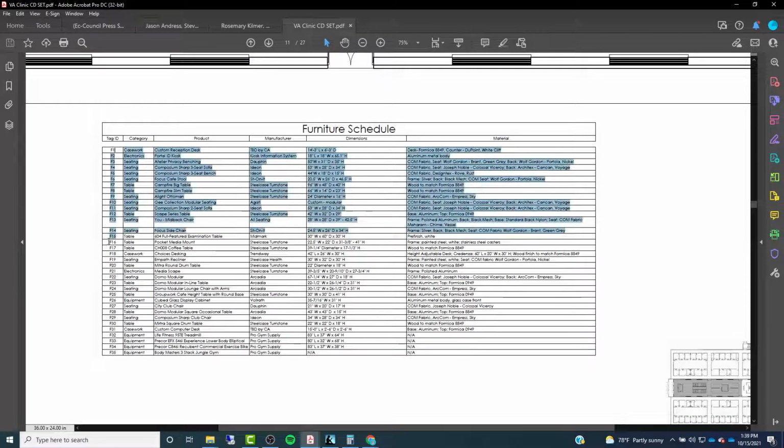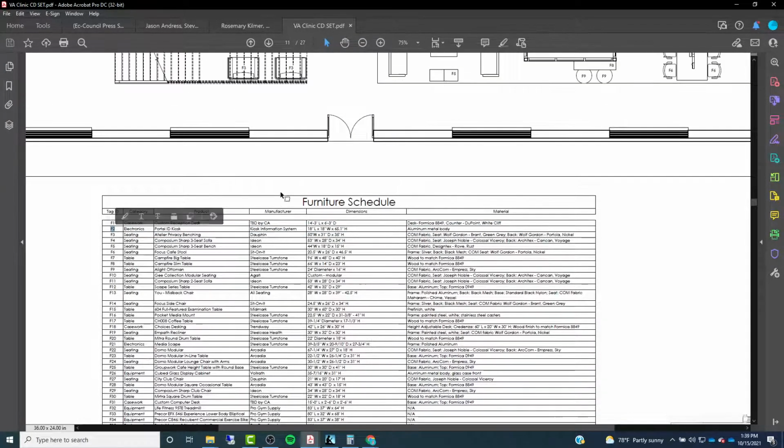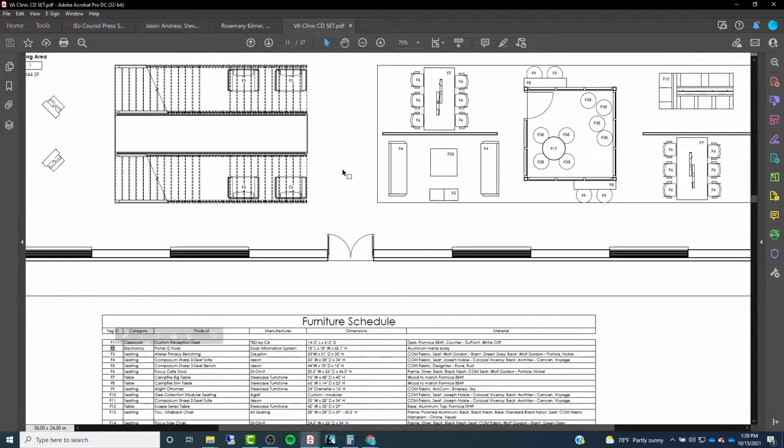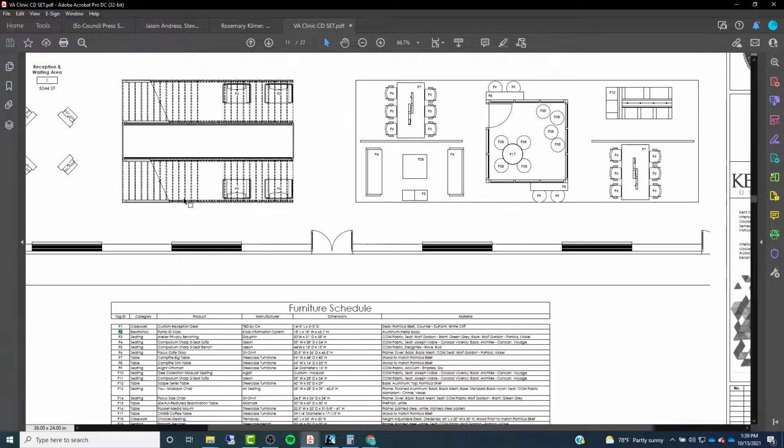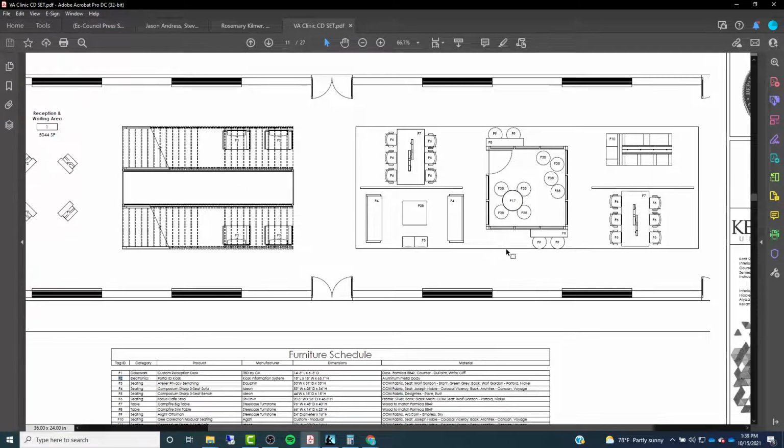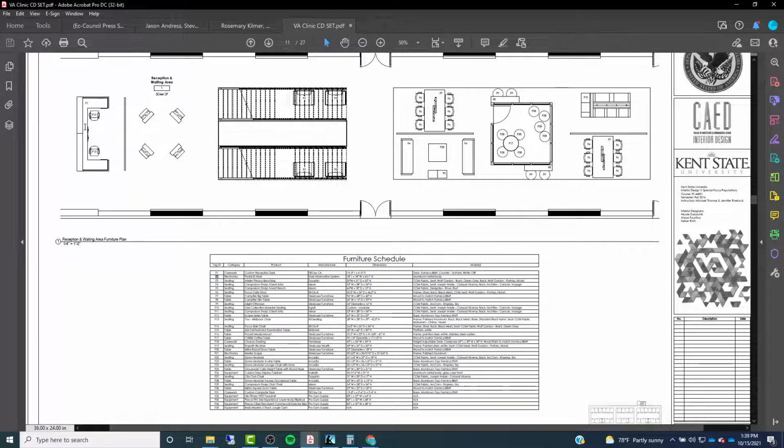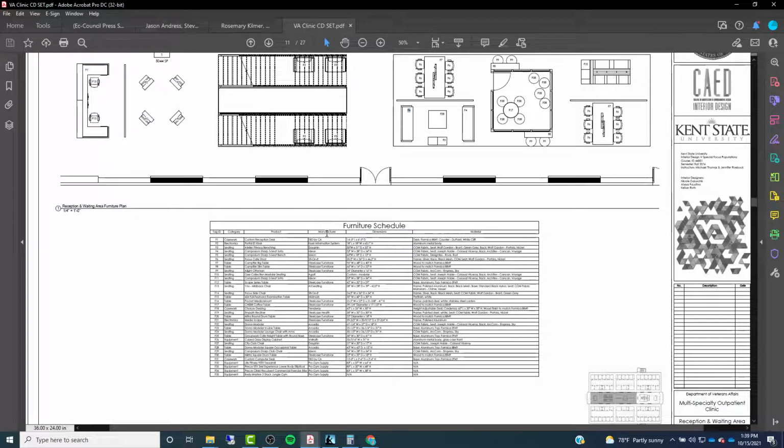And then you're just having these tags, really like coded notes. You're just having a little tag that's indicating what the thing is, and then you're applying that number to those individual objects. In Revit, adding these tags is a super easy process, and we're going to be learning how to do that. But you can expect to have a lot of these schedules throughout all of your sheets, because looking at a plan only tells you so much about what's going on. Really, you're going to need to go and get more information, and that information is going to be found in some sort of a schedule or a legend. Okay?